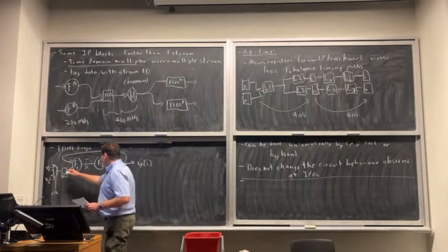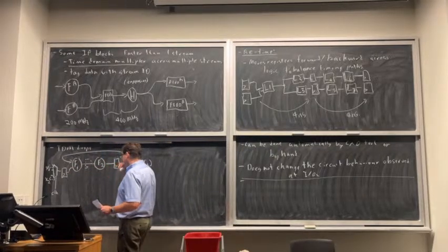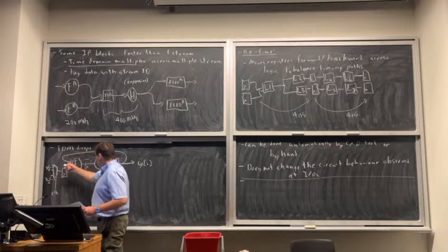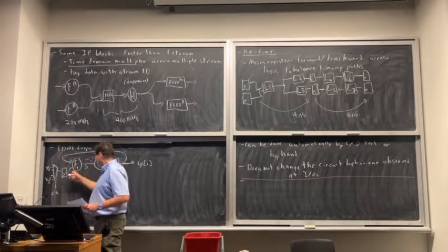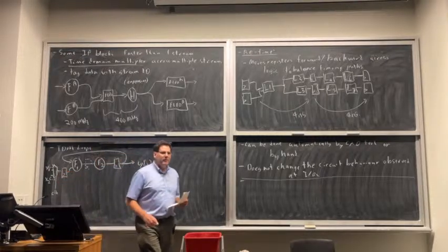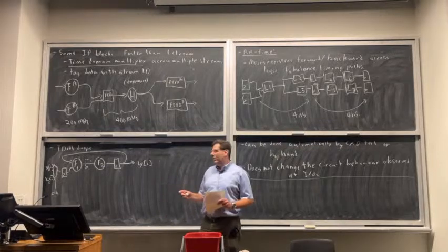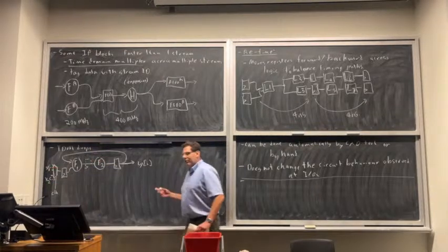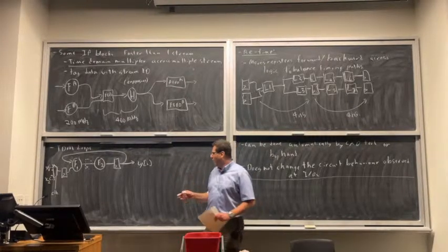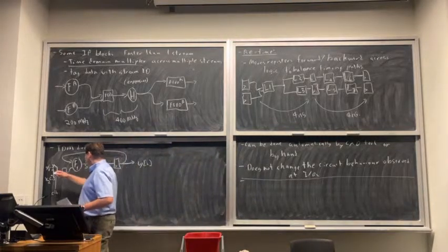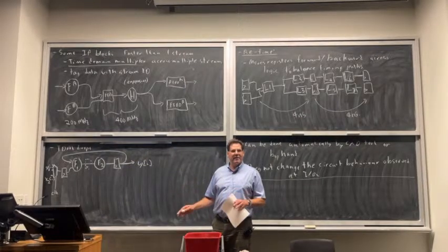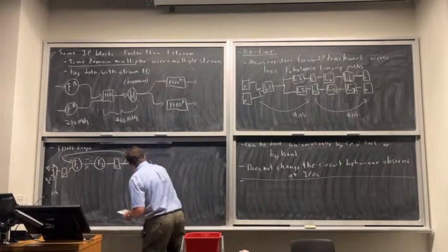So if you work through, what does that mean? By putting this extra register in, I'm actually computing Y as a function of my current output and something that happened two cycles ago. But the input I got two cycles ago, because I'm now sending in one stream one cycle and the other stream the second cycle, is actually the previous value in that stream. Okay? Does that make sense? So the combination of putting this register in and interleaving at the input between two different streams makes my latencies match up again. So I now get two output streams.